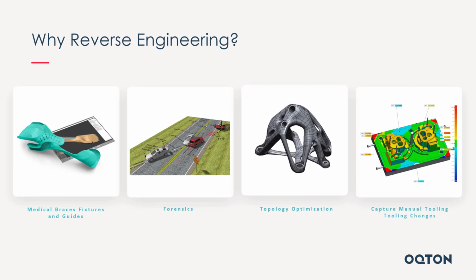Topology optimization. So in this instance, you can create different topology optimized parts. I think many people are aware that we're using simulation to create topology optimized parts, but the output of those softwares is usually polygons. So we can take those polygon models and clean them up and wrap surfaces around them and use that hybrid approach that we talked about before to then extract a good CAD model from topology optimized processes.